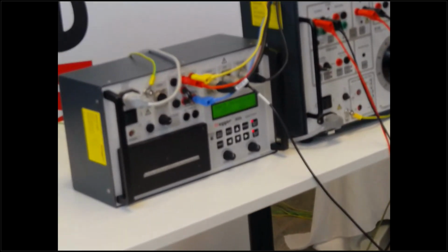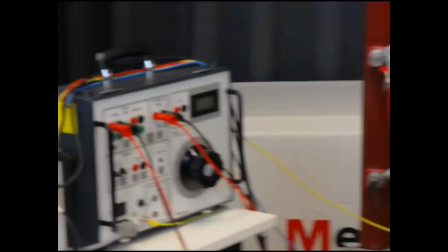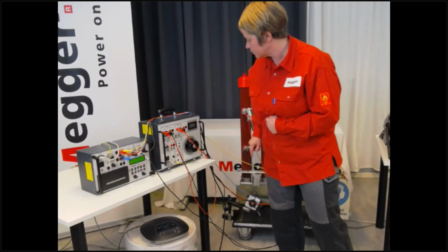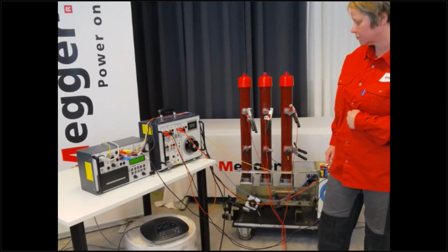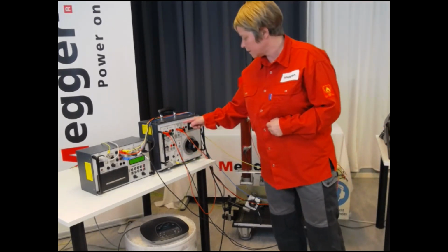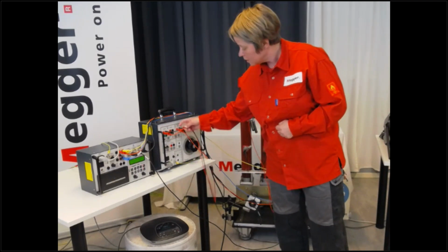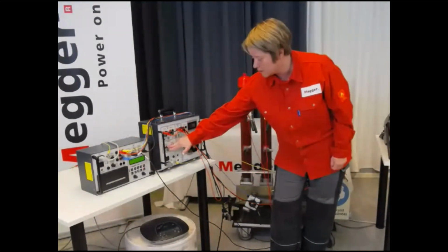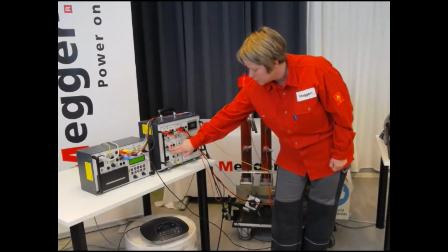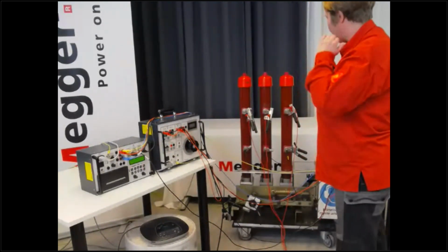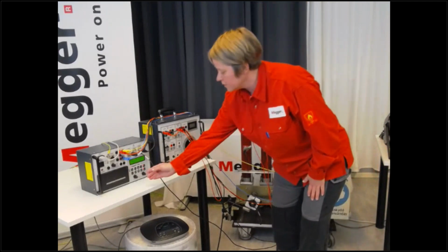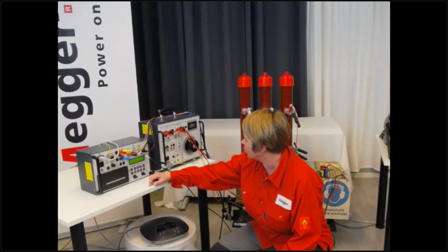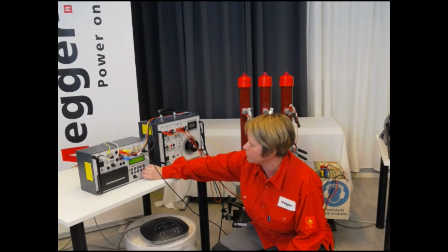What I need to do before I do any operations is charge the spring motor. So I'll make sure I have the motor turned on. A little bit of noise. And I move the voltage back to this outlet, to get voltage out here continuously, which I want now because I want to control on this one. I need to link here and make sure the contact setting is in contact position. And the breaker is open but charged now. So the instrument here indicates that it's not closed, right? And it wants to do a close sequence. So it's going to be a little noise. I have 110 volt and it's on coil. So I'm going to turn the knob and it's going to be a measurement.